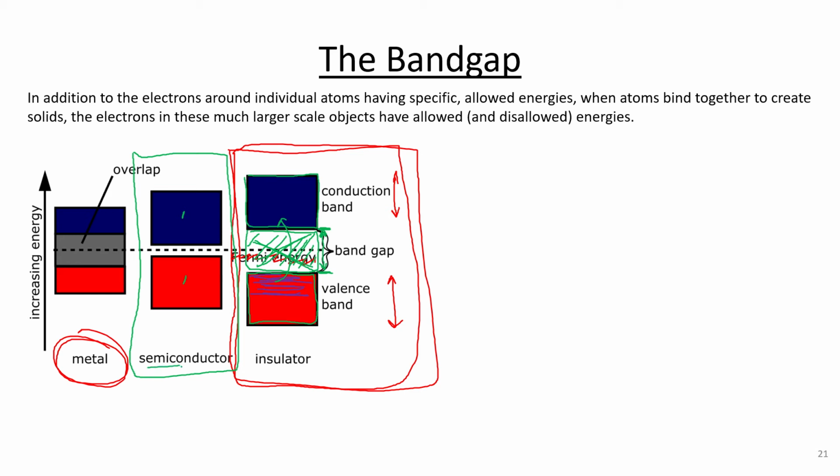Sort of what the name semiconductor implies. But this band gap, this energy gap between the bottom of the conduction band and the top of the valence band, is so small in the family of materials called semiconductors that you can put in just a little bit of energy. You can fiddle with them just a little bit in a lot of different ways, and you can convince electrons to go from the valence band, where everything is filled and bound to the atoms and nuclei and can't freely move. You can induce electrons pretty easily to pop up into the conduction band and move through the material.